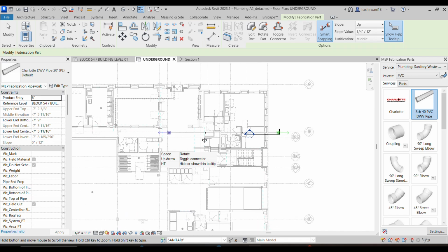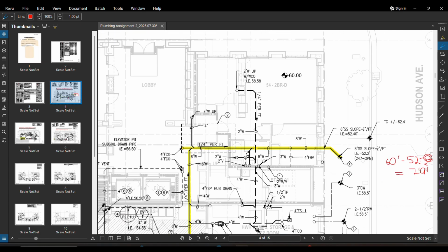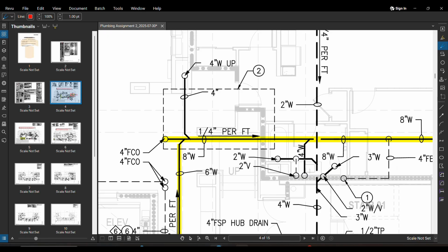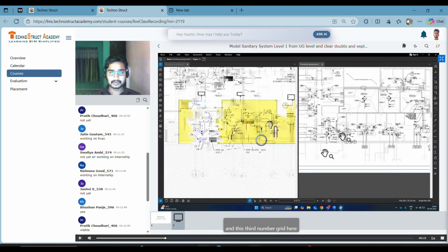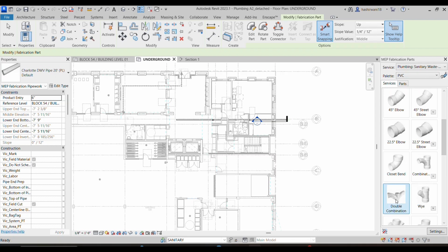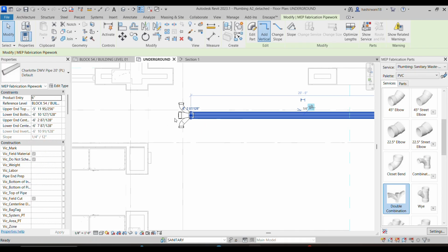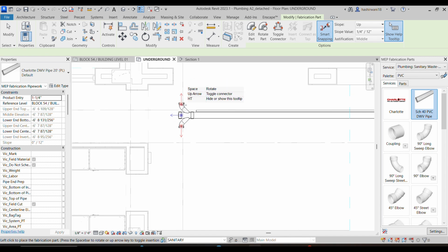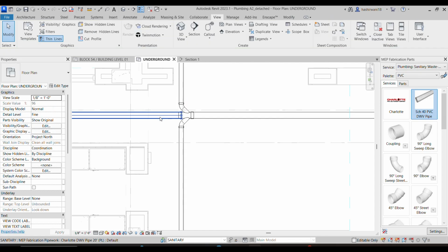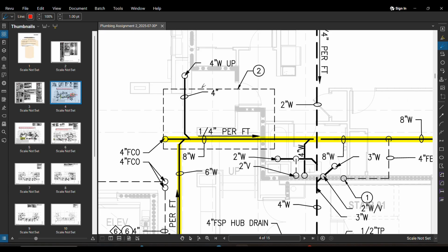And then I think it is moving in this particular direction. Now we have a sort of a double Y here. Sorry, I'll go back to my Revit, click on this double Y, select the correct size and then place it here. I'll select CS, which is create similar. I'll extend it on both sides and on this particular side as well, and then SL, which is slice, from this particular side. I'll check, so it is going up here, it is going up here as well. It is 4 inches, it is 6 inches, right?